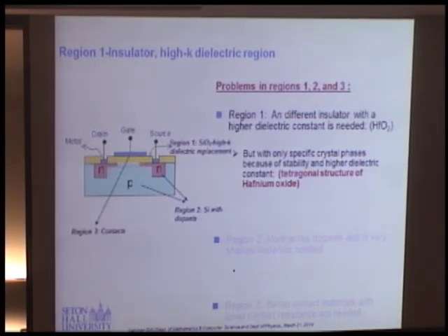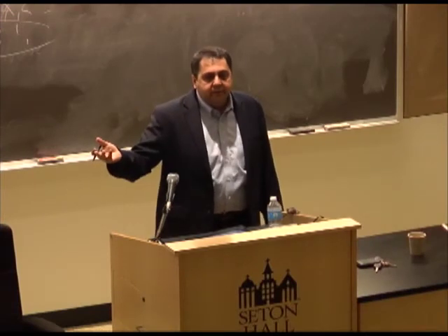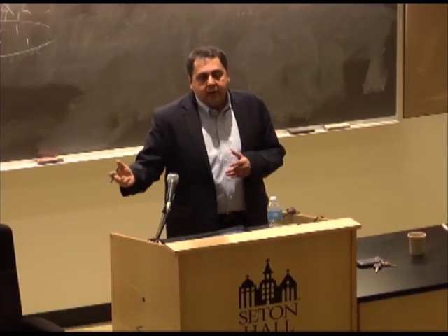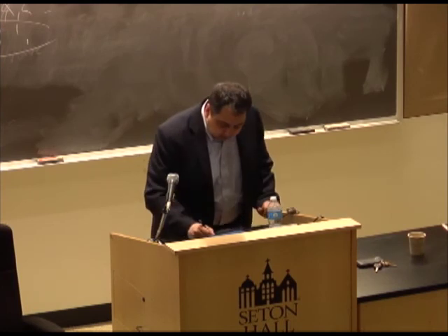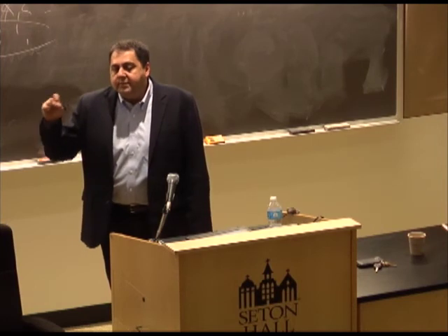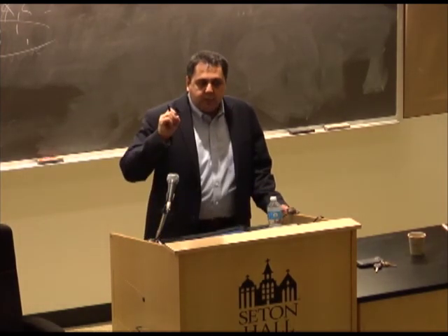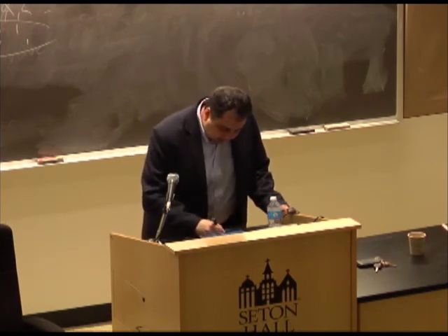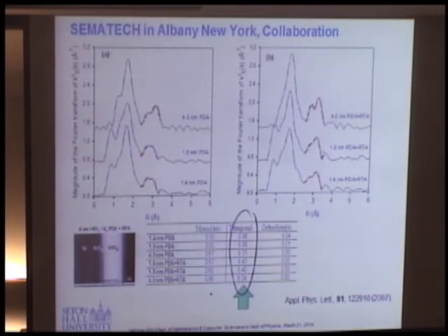one of the runs is to get the tetragonal phase of hafnium dioxide. We worked with Sematech a lot. They did their films. We did our films. We went to Brookhaven, looked at the structure, and finally we got this nice tetragonal structure settled, locked in with some kind of specific deposition conditions. And that's the phase, okay? You see the tetragonal, orthorhombic, and monoclinic. You see that there's a big competition between the monoclinic and tetragonal phases.